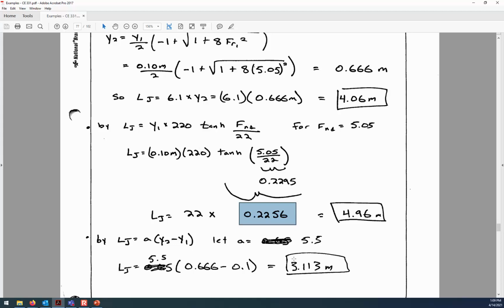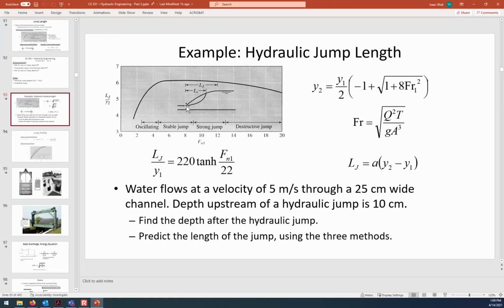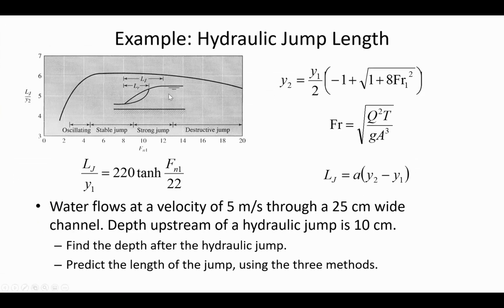Now, what it actually is in some cases is an art as much as a science, because it can be pretty subtle, the changes of depth as you're approaching. What we're looking for is when the depth approaches the normal depth. So here the flow is back to the normal depth. This last part of gradually varying flow, you're going to notice just a minuscule change in the water depth. It requires quite a lot of precision with a pin gauge to see how much the flow depth is changing from this point over to this point.